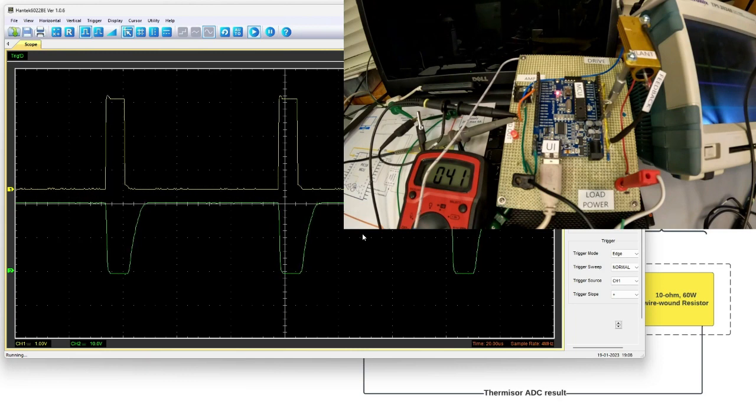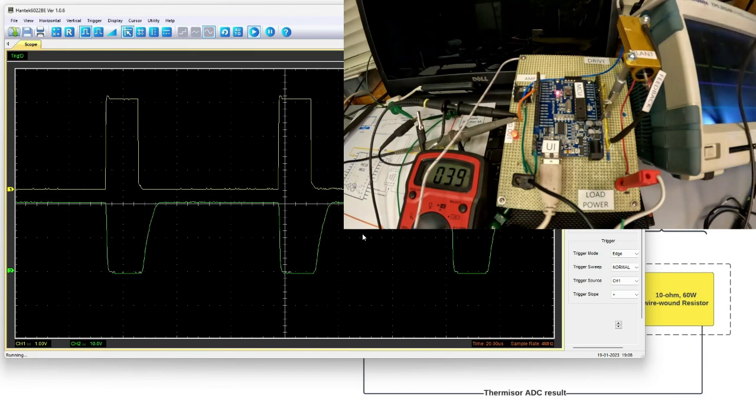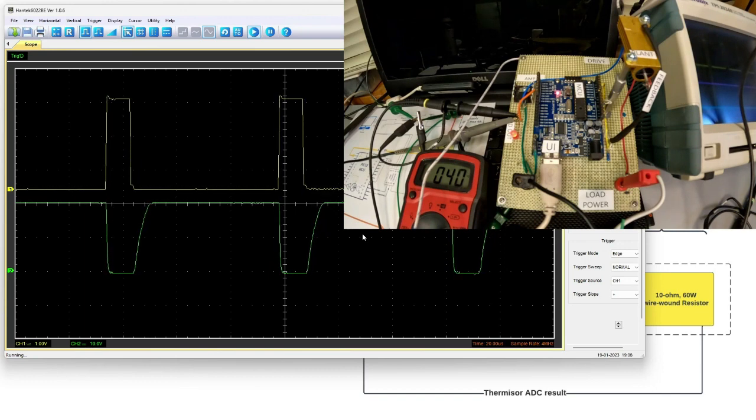Forced convection. Again, if I hit it with the air gun, I can introduce a fairly rapid deviation. You can see the pulse increase, and then it will regulate back to our set point, which is in degrees Celsius, nominally 40, 41 degrees. There are some imperfections in this loop, more on that later, but this is showing the effect of feedback to process that disturbance and then bring us back to our set point.